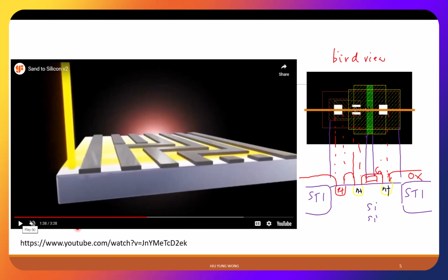You can do annealing, which means bringing it to very high temperature, and then they will just wiggle and eventually sit at the right place, just like cooking or whatever, right? So you can put it in a furnace. But now for advanced technology, we actually use laser. This is a laser anneal. They use the laser to heat up to very high temperature in a very short time, maybe 1200, 1100 degrees C for 1 millisecond.